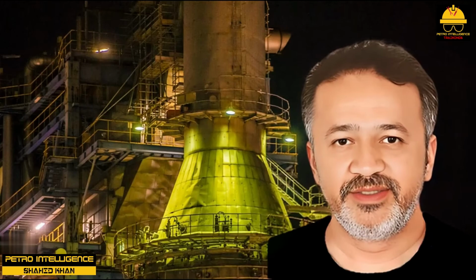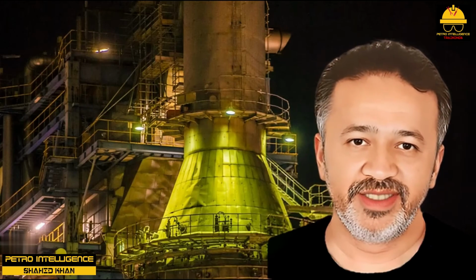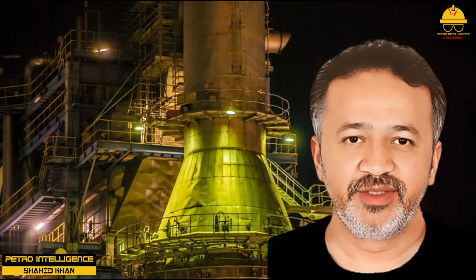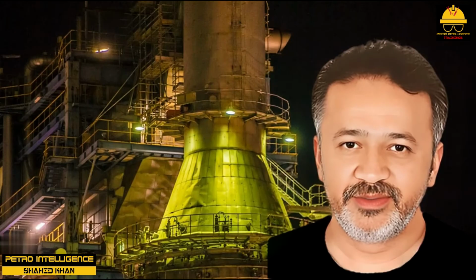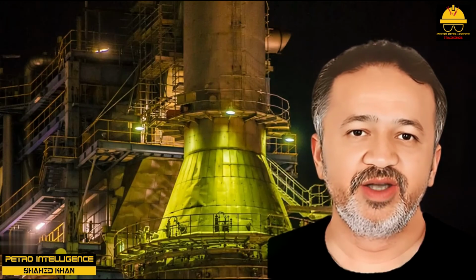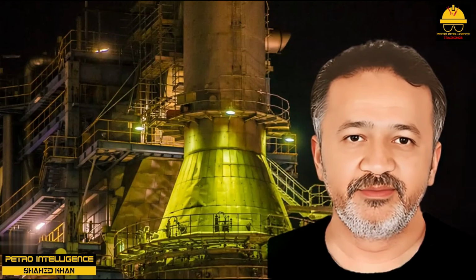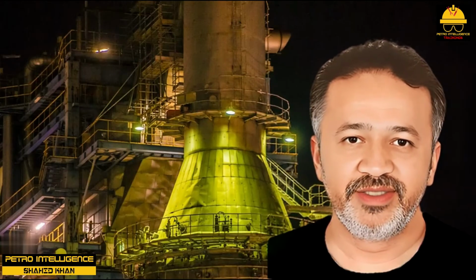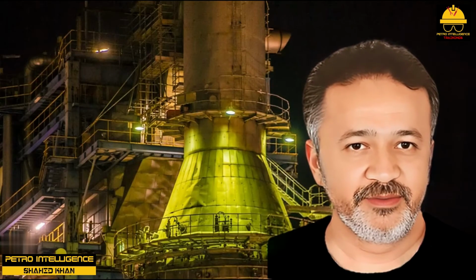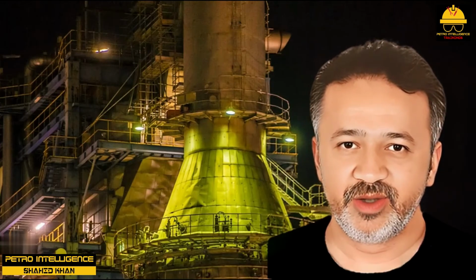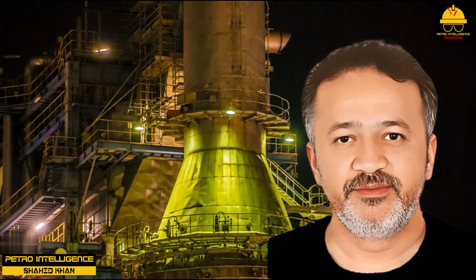Draft induced by wind. Running with a positive pressure below the bottom row of convective tubes is potentially dangerous, especially if there is an appreciable quantity of sulfur in the fuel. The sulfur dioxide would then blow out of the sight ports and leak into the convective section. SO2 is a toxic gas. In some texts, it is advised to maintain a minimum safe draft of 0.05 inch H2O.